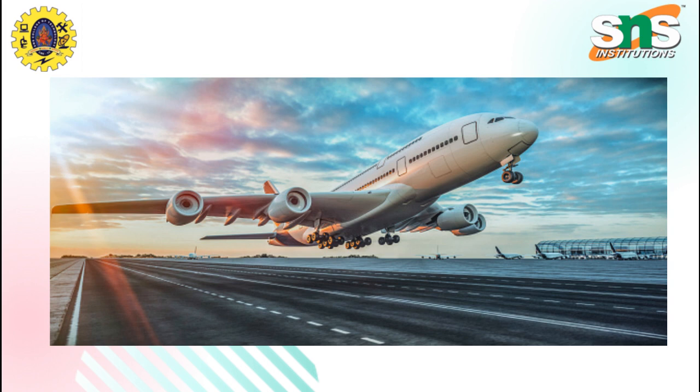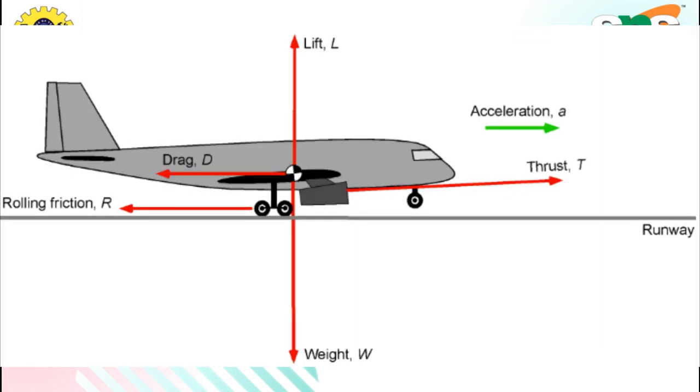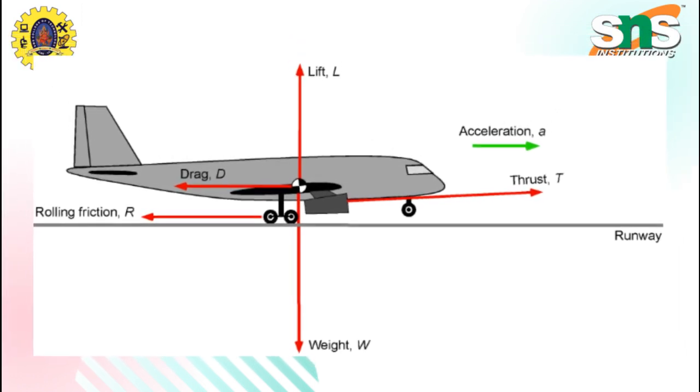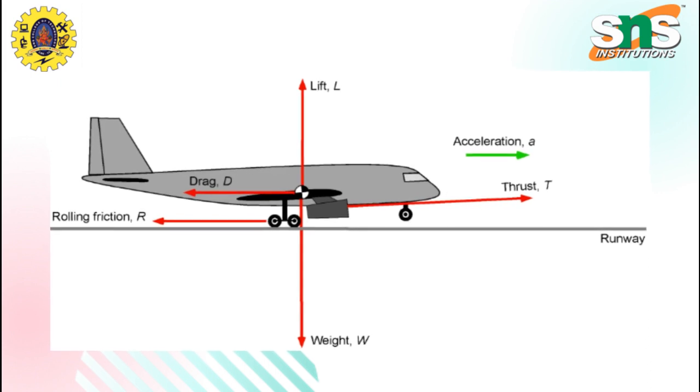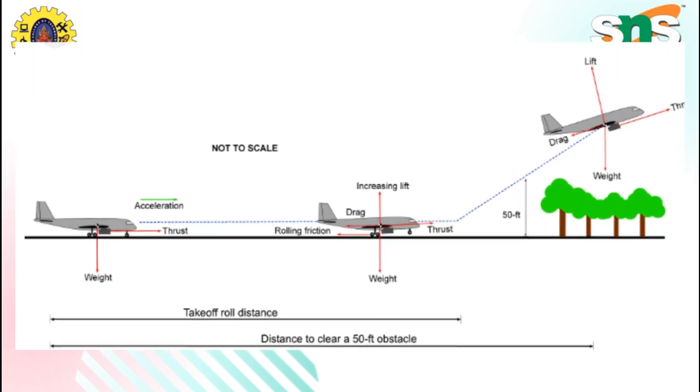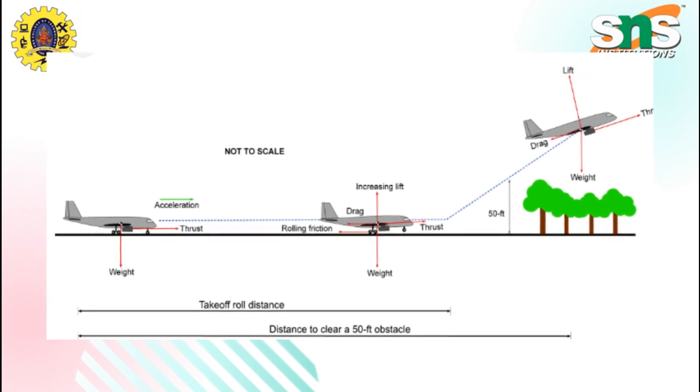The first step, determine the load. The first step in FEA is to determine the load acting on the landing gear. This load can be calculated using a mathematical model or experimental data. For example, the weight of the aircraft can be calculated using the weight and balance data, and the landing loads can be estimated based on impact velocity and aircraft weight.